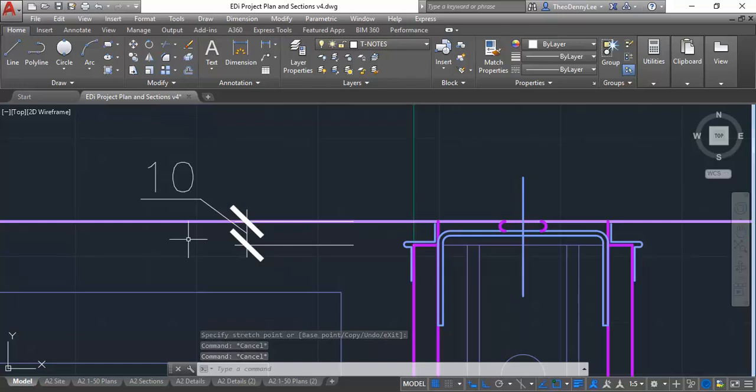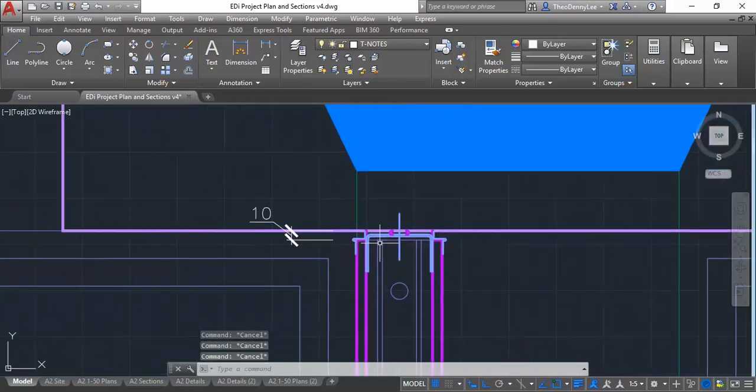Which option? No, you haven't got ISO. ISO or horizontal, yeah. Okay, so that's all you need for dimensions. You do have ISO. Then go to the next tab, the Fit tab, and choose with leader. Yeah, that's it. Just go OK, and then close. No, that's fine. Just close that.